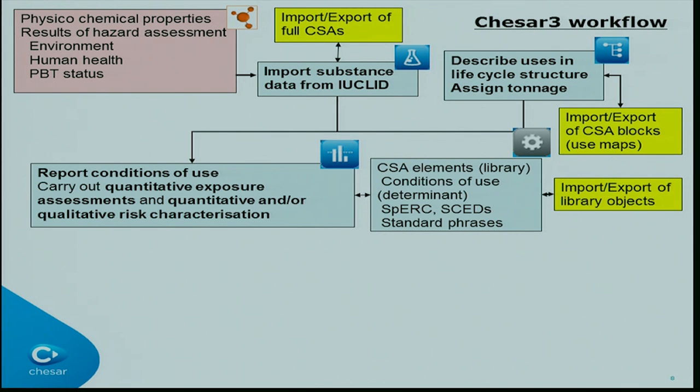For this, exposure assessment can be of quantitative or of qualitative nature, depending on the type of hazard. If you have a DNEL or a PNEC, then you have to ensure that the exposure is below the DNEL or the PNEC. If you don't have that, for example, local effects, thermal irritancy, then you have to carry out the qualitative risk characterization. This is something which is not that straightforward, but not so complex either.